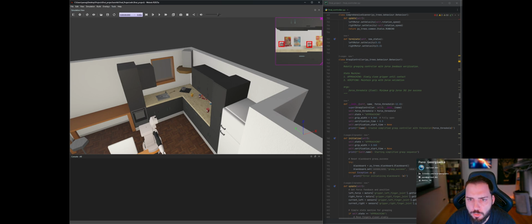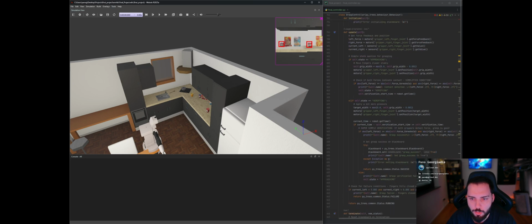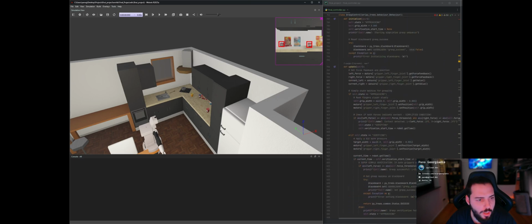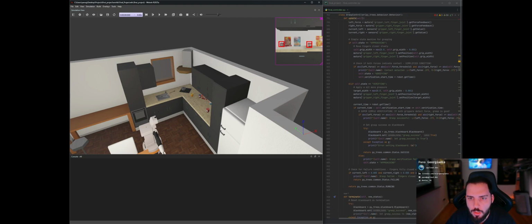Moving on to our grasp controller. This is a robotic grasping controller with force feedback verification. When approaching, it will make sure that the gripper is fully open. And then it also verifies, as soon as the gripper closes on the jar, or where it thinks it should have a jar in between its gripper joints, that it's not fully closing. This could be either via force feedback or via position, where the open position is 0.45 on the gripper joints and the closed position would be 0. So if it's not able to reach 0, then clearly there is something in its hand.